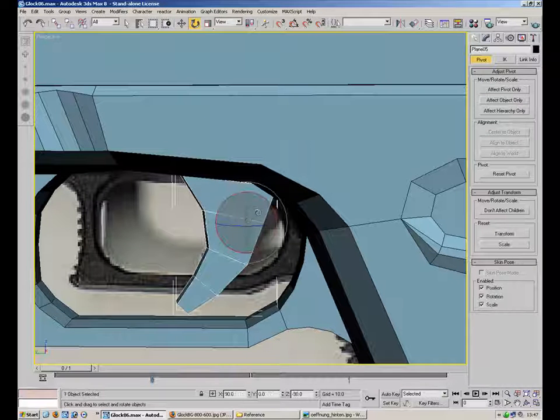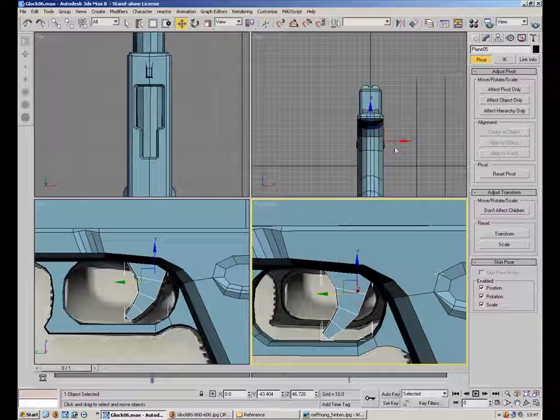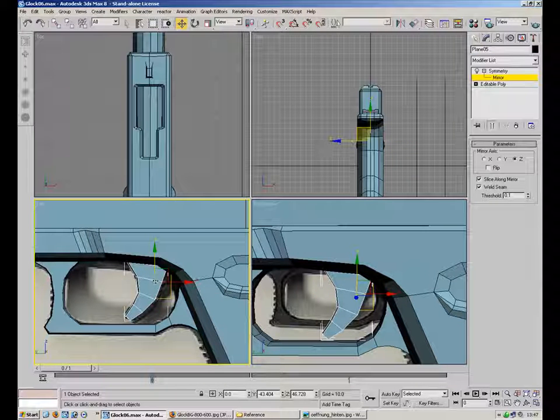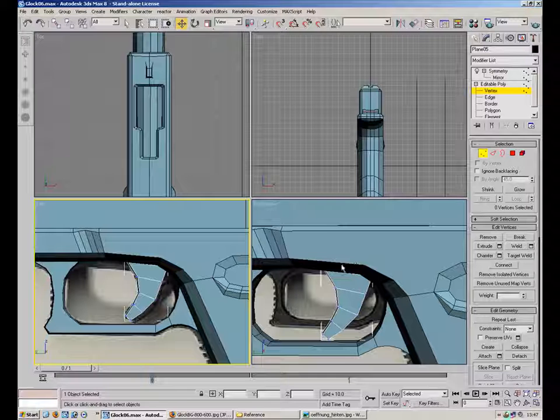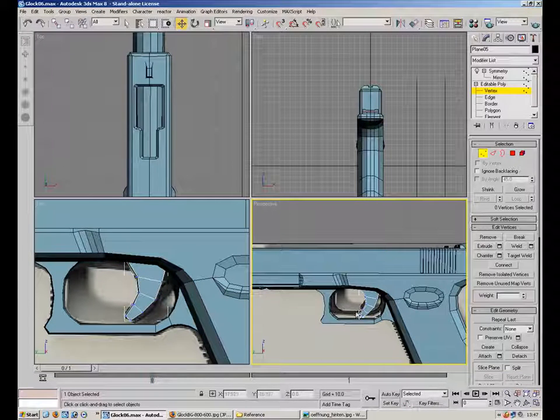The animations are all done from bones, and the movement of your geometry will be calculated from the pivots of your bones rather than the pivots of the objects, so you don't need to worry about that, and we'll go into that more when we actually do some animating.